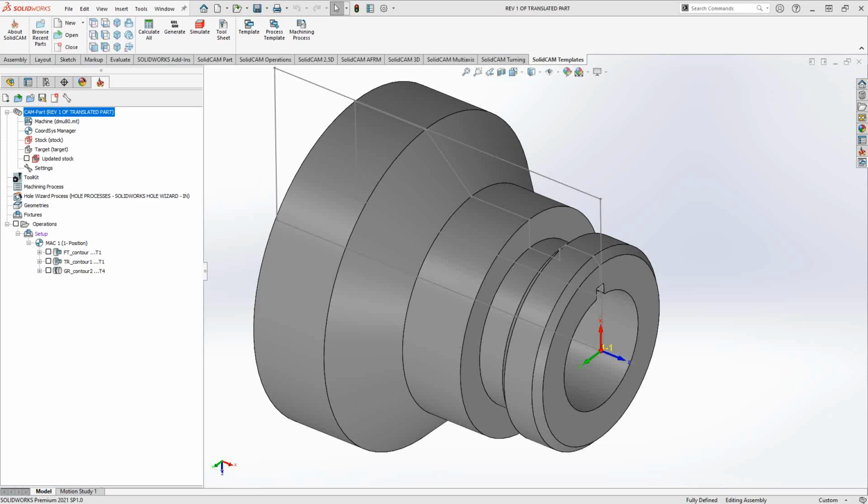So we've seen in previous training videos and CAD/CAM videos where there is a level of associativity that SolidCAM has with the original SolidWorks part, and how when you change that model, that associativity will update your toolpath. Now, the way that actually works is in the background, inside SolidWorks, every face, every edge, every sketch entity has an ID number.